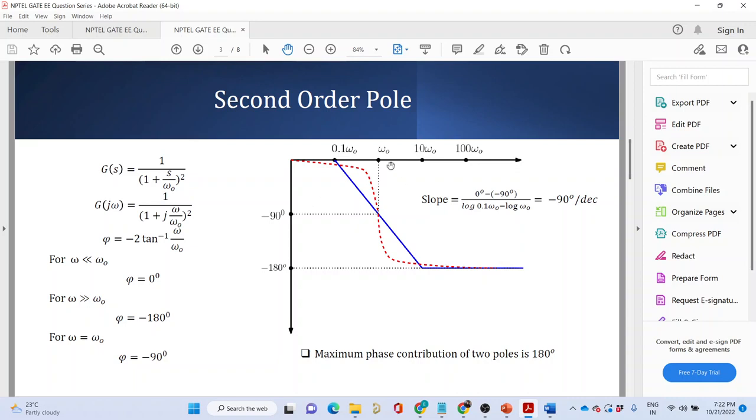Okay, so this Bode asymptotic plot is fairly accurate when there are real poles. When there are complex conjugate poles, you cannot say, because the slope will depend on zeta, the damping. So you cannot quantify that by your approximation. Okay, so this is the basic idea.